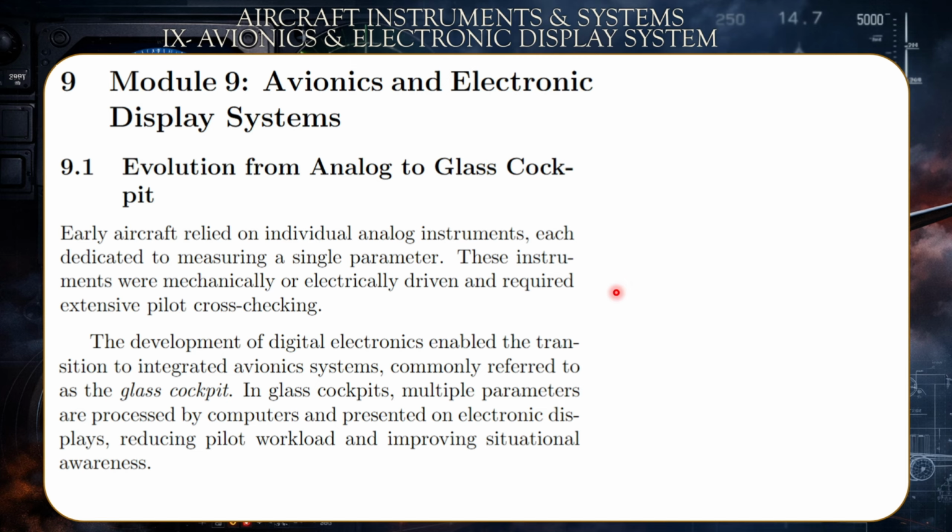Another side note I want to talk about is the term situational awareness. So, what does it truly mean? Situational awareness is the understanding by the pilot of the different conditions of the airplane when it comes to the attitude, okay? So, whether the aircraft is pitching up or down, if it's rolling to the left or to the right, if it's skidding, okay? That's one. Second, the airspeed. And third, the altitude, along with the VSI, vertical speed indicator.